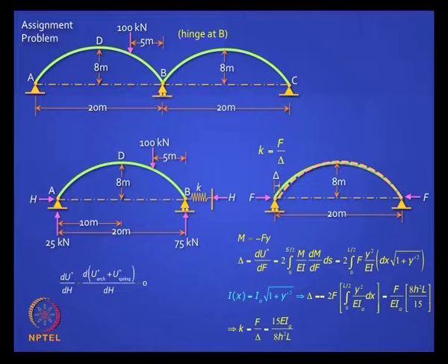That is the addition term. This is how you should think, because real life problems are like this. You want to simplify it, this is how you deal with it, otherwise you have to work with both the arches. Now if you run that derivative through the second term, do you agree the spring energy is half h squared by k, because the force in the spring is h, you agree, and the derivative turns out to be h by k, which is nothing but the deflection in the spring, right.